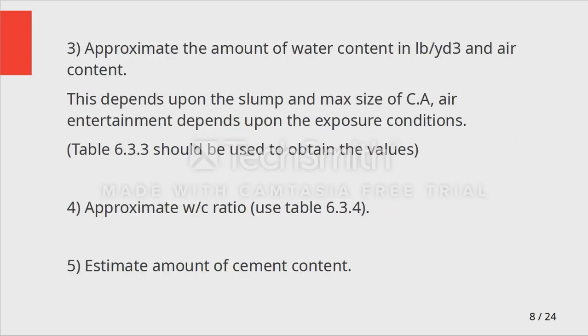Similarly, you need to approximate the amount of water in pounds per cubic yard and the air content. This depends upon the slump and the maximum size of coarse aggregate. Air entrainment depends upon the exposure condition. Table 6.3.3 should be used to obtain the value. So water content and air content basically depend upon the slump, maximum size and exposure condition.